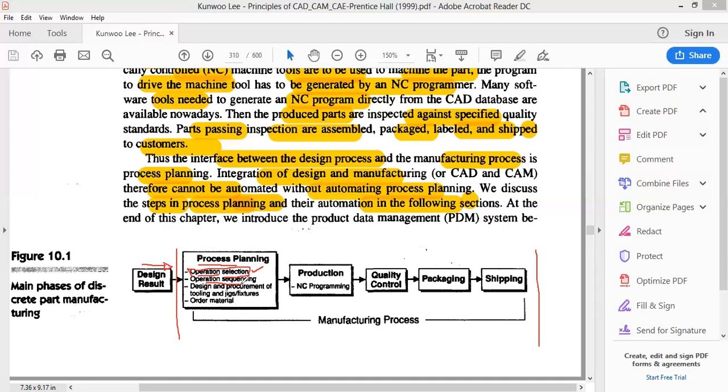Now if you say that it has to undergo, for example, if we have the body of the engine, right? So the body of the engine has to undergo slab milling, and the edges have to be finished without any sharp corners. Then it also has to undergo many different types of drilling operation. In some cases only normal drilling, in some cases boring operations, and in some parts drilling for only a particular depth, not for the complete end to end. The drilling has to take place, right?